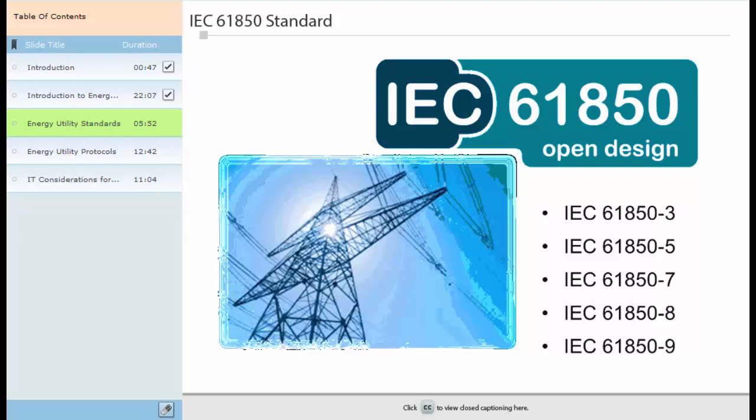IEC 61850 has been divided into 10 parts. The most important aspects of communication within IEC 61850 are covered in the following sections. IEC 61850-3 provides the general requirement for the substation automation equipment. IEC 61850-5 provides the communication requirement for the devices. IEC 61850-7 defines Goose and GSSE that are substation event message services. And lastly, IEC 61850-8 and -9 provide the specific communication service mapping over Ethernet.